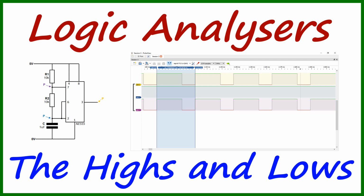In today's video, I'm going to quickly introduce a very useful tool in digital electronics, which is the logic analyzer. If your interests as a hobbyist lie mainly in working with digital systems such as microcontrollers, you can definitely afford to buy a cheap logic analyzer from eBay for $10 or maybe a bit more. You can then download free software called PulseView, which is very powerful and open source and allows you to interpret common protocols.